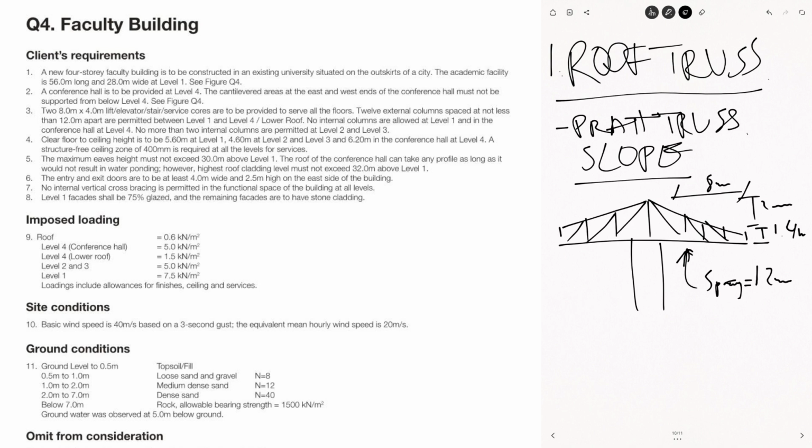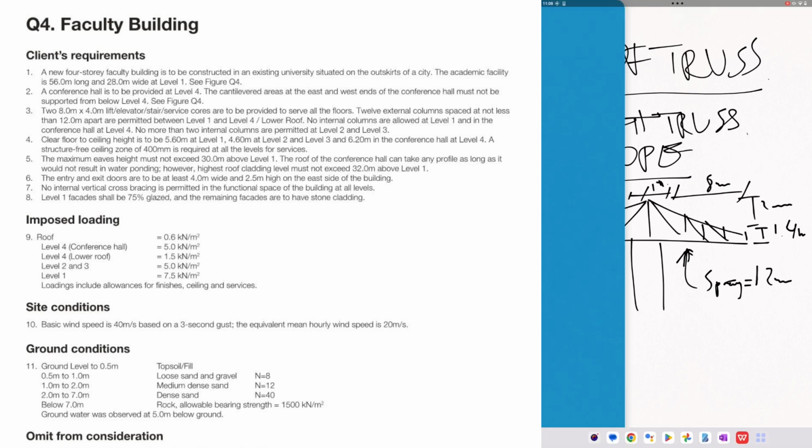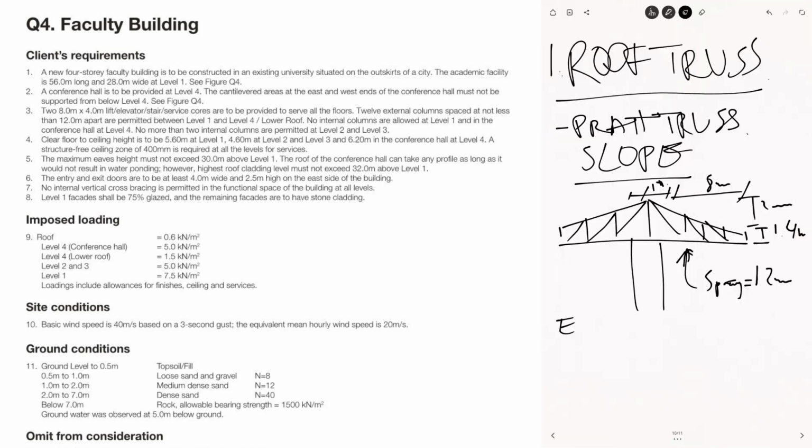The reason is that even though the cantilever span is 8 meters, and I think the maximum span in between was 14 meters, the effective length of the cantilever is actually double the actual span. So instead of 8 meters, the effective length would be 16 meters. But for our calculations, we will use the 8 meter value, unless we need to use the effective length.